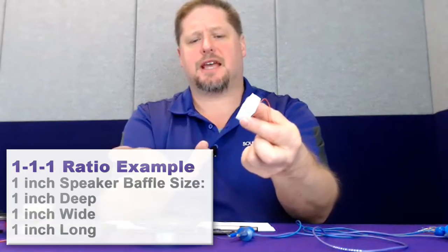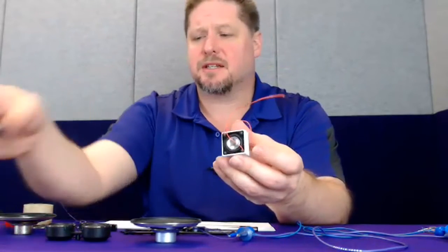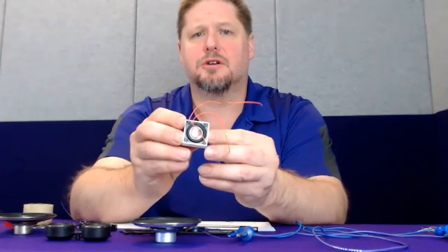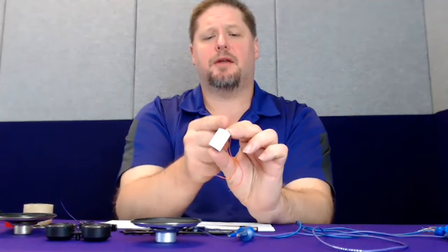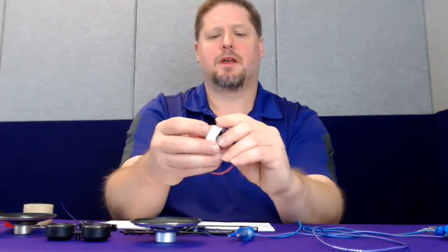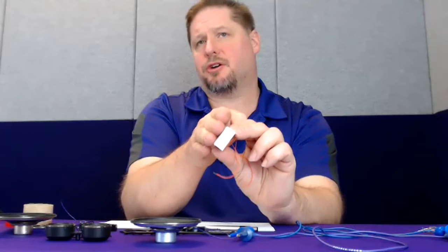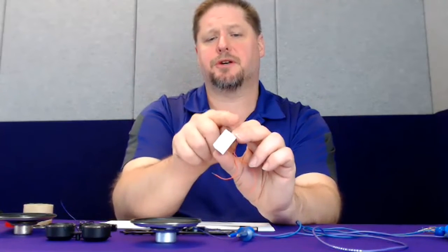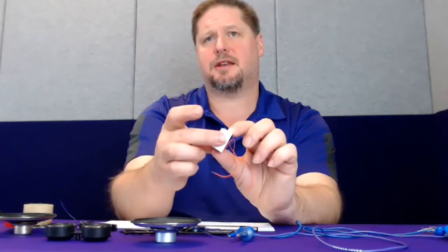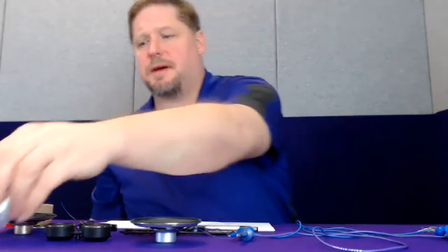So you've got different examples here of what you can do. These Mega Bass speakers, for example, don't easily fit into an HO narrow hood diesel. So what you can do is take this speaker and mount it at an angle and build a custom baffle that would fit inside that hood housing, so that way this speaker can fit in there. Your housing doesn't have to be square every time like this. So if you build it to fit inside that narrow hood diesel with an angled baffle and a custom build, you can fit this into just about anything that you're looking for.